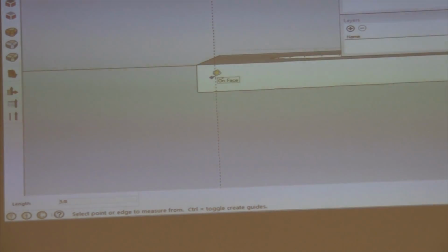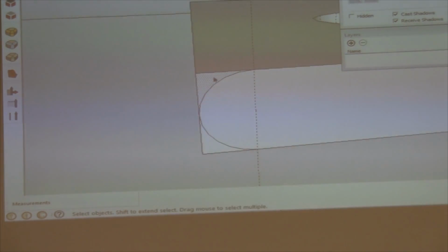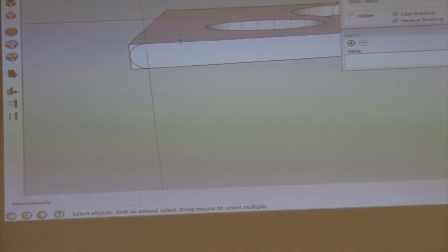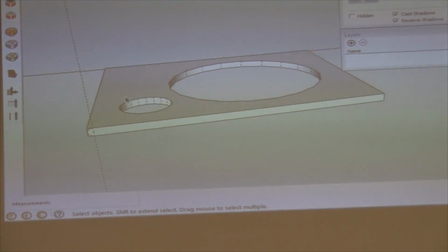And I'm going to draw an arc that goes from this point to this point out 3/8 of an inch. It gives me a perfect 3/8 inch bullnose, right? From here, I want to basically take this profile that is right here, and I want to push it along all three, not 4 surfaces or lines on this surface.